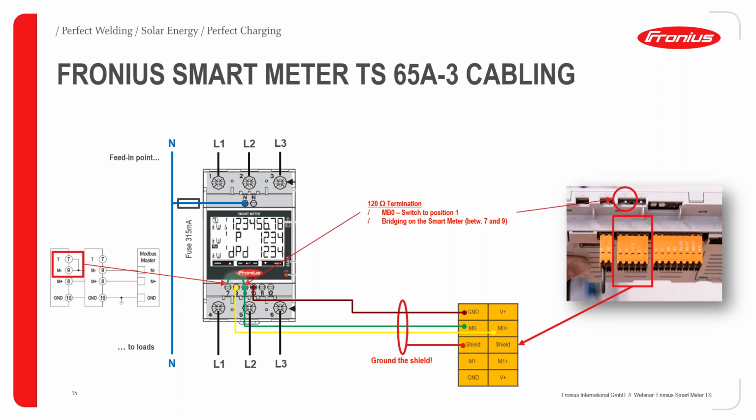And the third one is actually not listed here, but in the next slide. Always use a twisted cable pair between data plus and data minus. For that, we recommend using a Cat5 cable or a higher standard because they already have these twisted cable pairs inside.